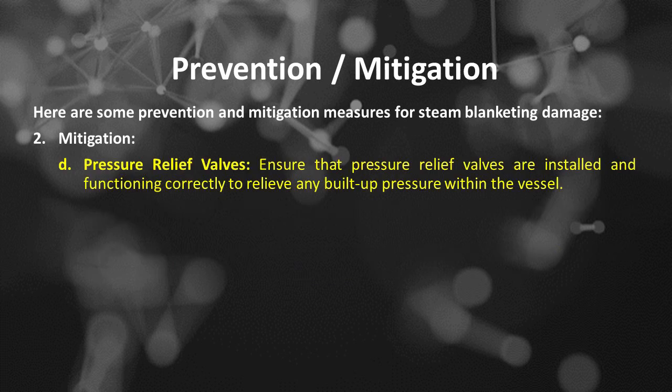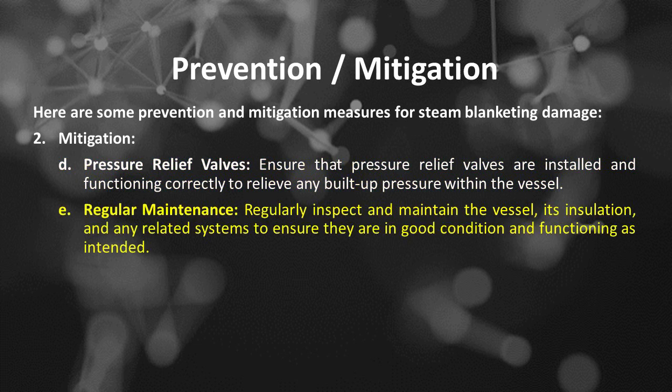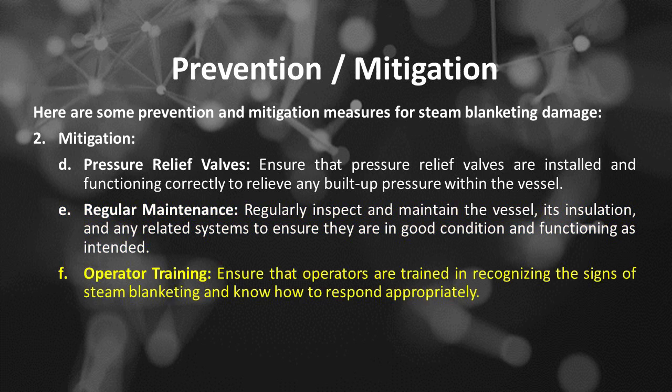The fourth is pressure relief valves. Ensure that pressure relief valves are installed and functioning correctly to relieve any built-up pressure within the vessel. The fifth is regular maintenance. Regularly inspect and maintain the vessel, its insulation, and any related systems to ensure they are in good condition and functioning as intended. The sixth is operator training.